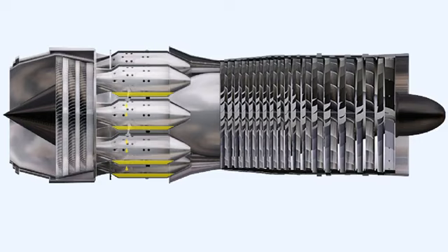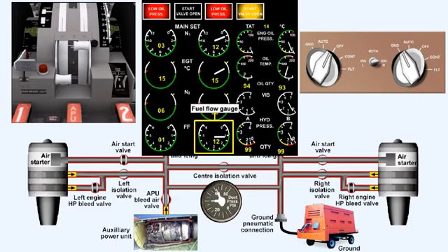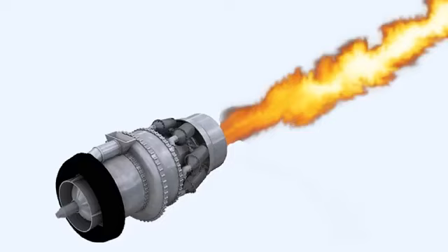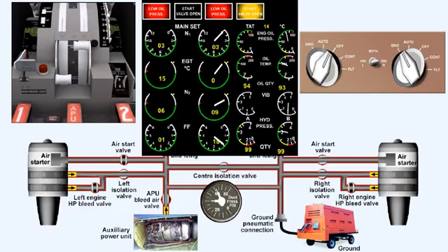Throughout that period, the combustion chambers and exhaust system are becoming saturated with fuel. The fact that fuel is entering the engine can be confirmed by a glance at the fuel flow meter indication at the instant of moving the start valve to the idle detent. Two dangers exist if this fuel is ignited. Firstly, it will cause a very large jet of flame to issue from the exhaust system, the phenomenon called torching. And secondly, the rise of EGT may well be uncontrollable and could exceed its limitation.